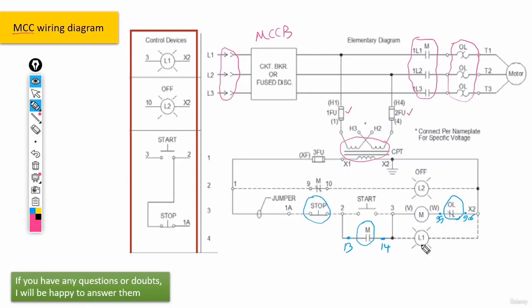We also have some signal lamps, guys. When the contactor starts working, these lamps here would be turned on. Okay, and we also have another signal lamp set up here on this line. And if the contactor was turned off, or if it was deactivated, for example, this contact here would work, and this makes the signal lamp turn on. And if the contactor was activated again, the contact here would be opened, and as a result, the signal lamp would be turned off.